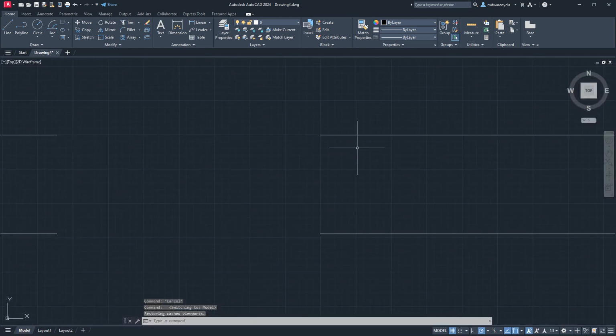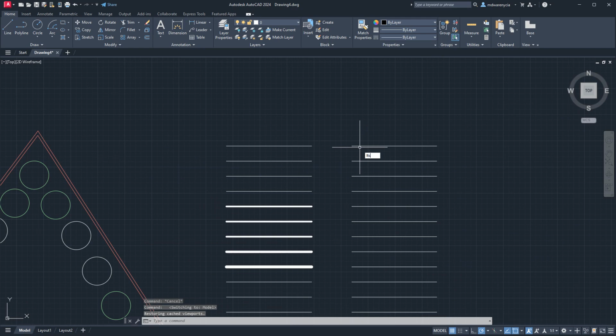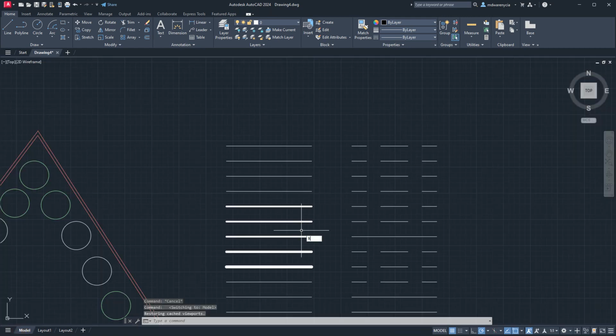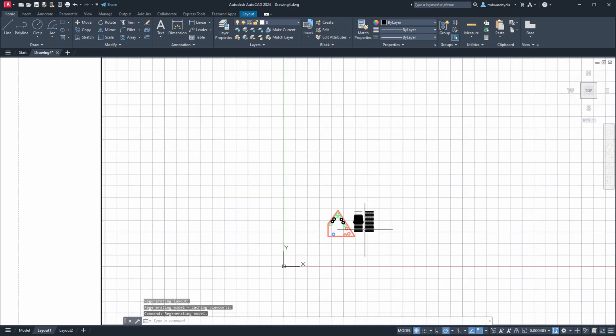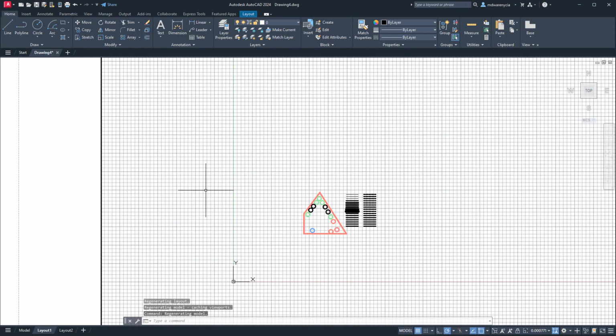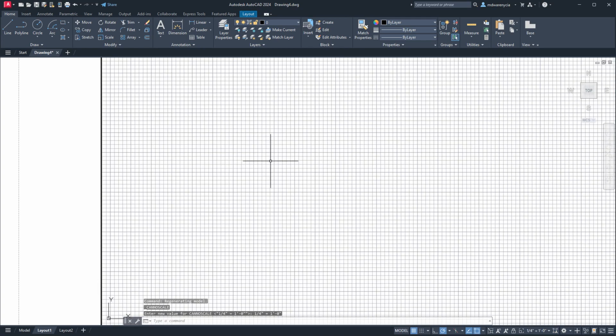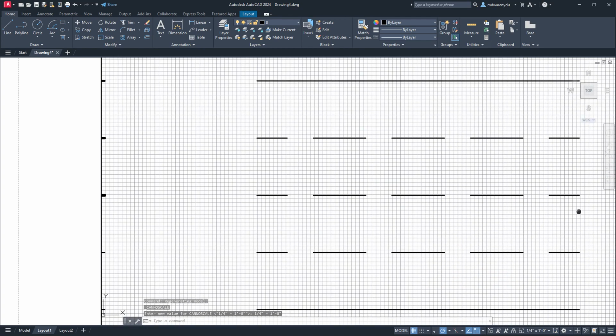I've got a guide, I'll pass it out to you guys. LT scale 64. There we go. So then LT scale, scale 32. Eventually, you just basically find out the scale that works for the lines that you're using, and I've got a guide that walks you through this, because naturally all the lines have their own scaling algorithm that they use.